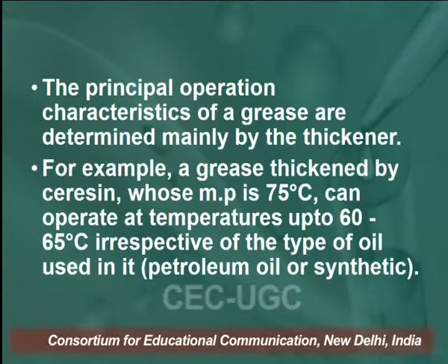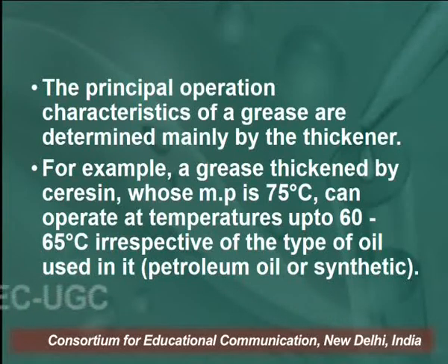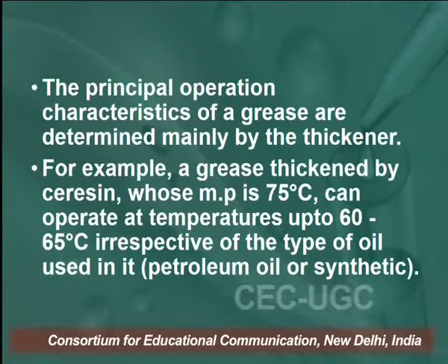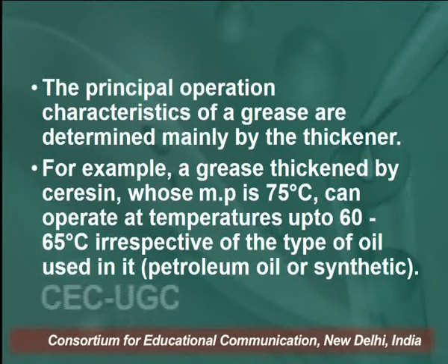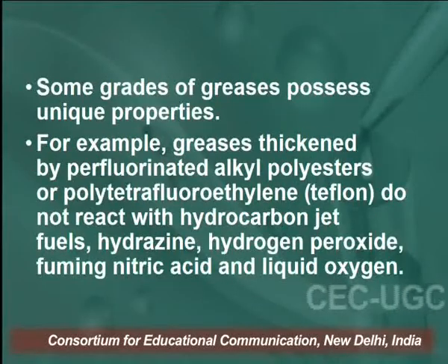For example, a grease thickened by ceresin, whose melting point is 75 degrees centigrade, can operate at temperatures up to 60 to 65 degrees centigrade irrespective of the type of oil used in it, whether it is the petroleum oil or the synthetic oil. Some grades of greases possess unique properties.